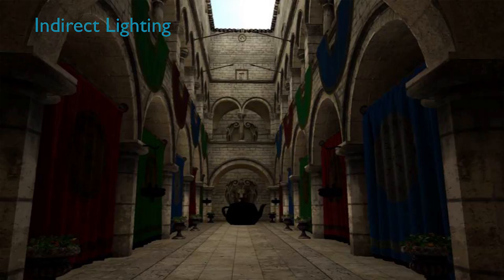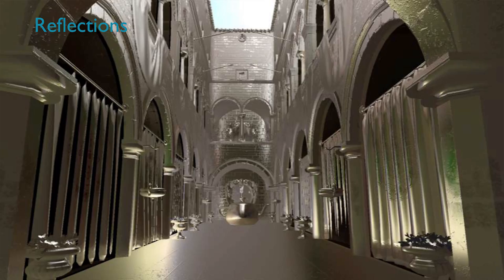And here's the lighting contribution of the indirect part of the scene. Here we use the lighting reflected from the direct lighting plus lighting from the hemisphere. We can also render the hemisphere into the probe relighting mechanism to get indirect lighting from the hemisphere. This is the reflection part that's generated from the runtime. This is a bit exaggerated just to show how it works. You can get crisper reflections as well, but this particular scene used very rough surfaces.